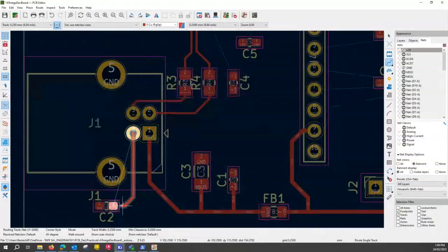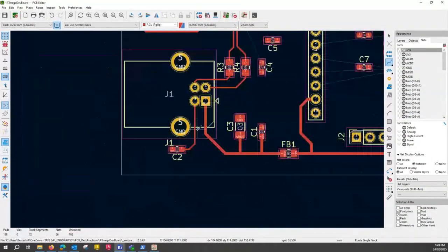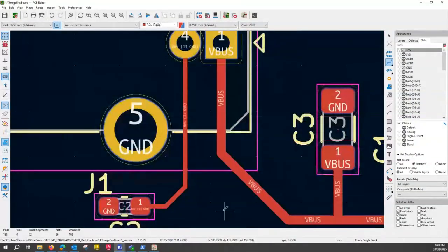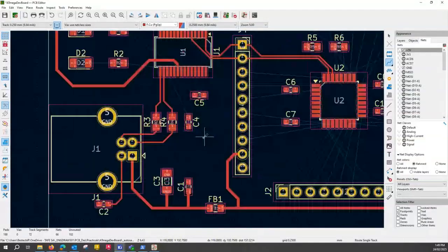So what I'll do is I'll connect it like that using thin track. It's ground, but it's different ground to your board ground. That's why we're using the net connection. That ground is the same as the board, so we don't have to manually allocate it. It will automatically join everything together. The system will. So this part is done.